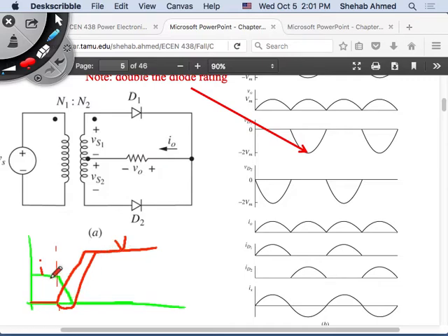So current is falling down. You've given the device a signal to turn on, but this circuit has delayed the rise in voltage. So it will have some capacitor somewhere to change the rate of voltage rise. And what did this cause? It caused that now I have this waveform and this waveform. Now I never have a period where I have voltage and current together. Here I have current, 0 voltage, 0 voltage, all the way until here. So switching losses are reduced this way. So I'm able to delay voltage.